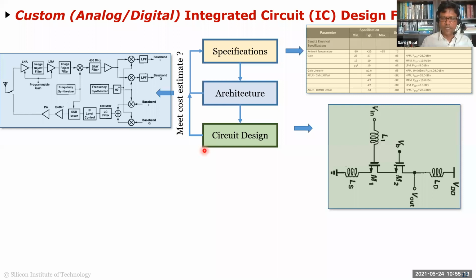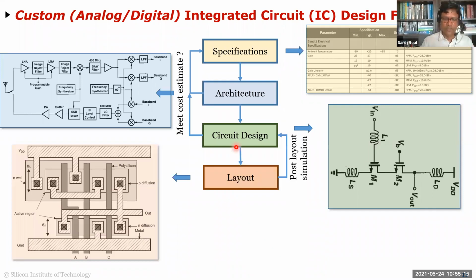And then once you get satisfied, and obviously you'll be running simulations to make sure of this. These are circuit level simulations like SPICE or Spectre or Aldo. These are simulators from different companies. You do that, verify, and then this is an abstraction in the sense that when you're going to send your circuit for fabrication to the fabrication house, let it be TSMC or Global Foundry or IBM or whatever those foundry houses are, you can't send them these. Okay, they don't know what to do with this.